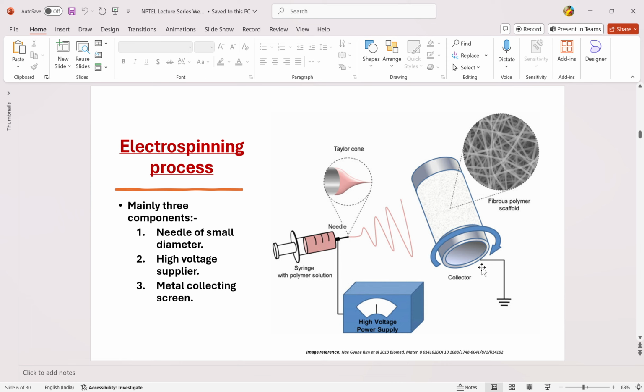After you have formed nanofibers, the first characterization you should do to see how well your nanofibers have formed is SEM. So this is a SEM image. This is not a drum collector image, because with a drum collector, the fibers will not be deposited randomly; they will be deposited in a particular direction. So this one is a plate collector image.